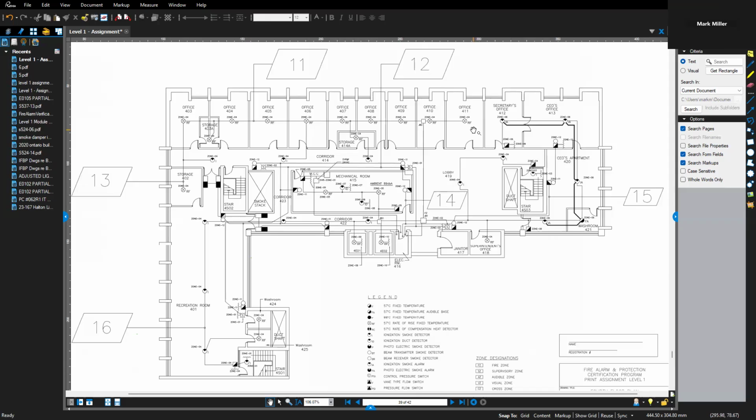However, in a group C major occupancy, all rooms not within the actual apartment or suites of residential occupancy have to have fire detectors in them. And this building is unsprinklered, so we have to put a heat detector in, which is why we have so many devices, because it is a group C and group D major occupancy. Right, so that is one part of a little bit weird in this building.